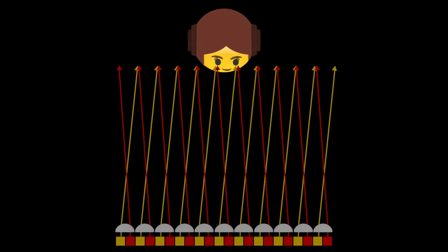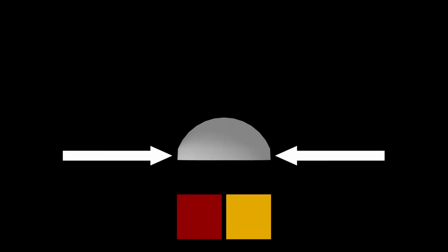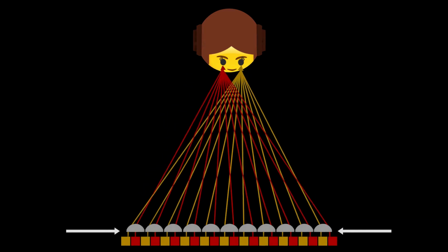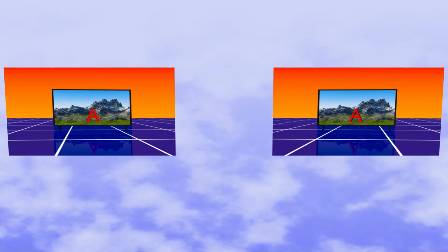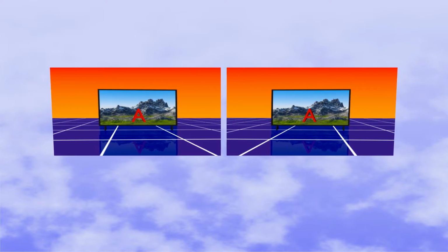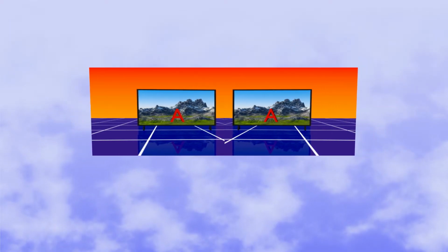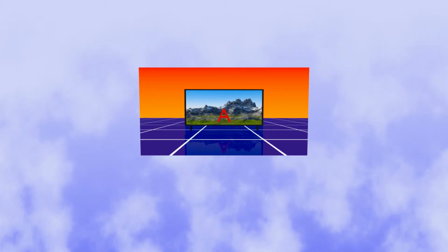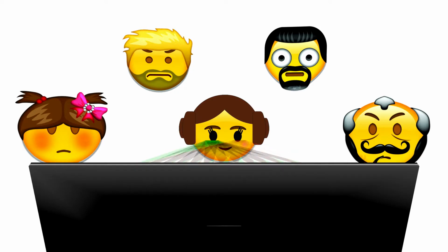To achieve this, the width of the microscopic lens is made slightly narrower than the combined width of the two corresponding pixels, and the width of the lenticular layer is made slightly shorter than the width of the pixel layer. Once the lights are focused, each eye will see a single image. The two images are slightly different, and the observer's brain combines the two images together to interpret them as a single 3D image. The problem with this technique lies in the focusing method.